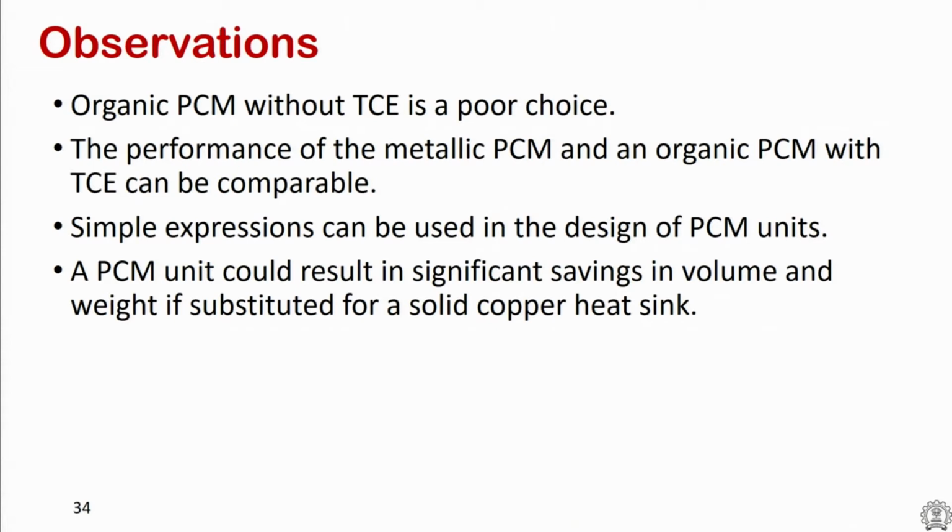As we talked about, one of the observations from this simple application is that organic phase change materials cannot be used for transient electronics cooling applications, and one has to either improve their thermal conductivity, which is typically about 0.2 watt per meter Kelvin for organic phase change material. So, one has to integrate some foam or something to improve its thermal conductivity, or one has to use some sort of a metallic alloy.